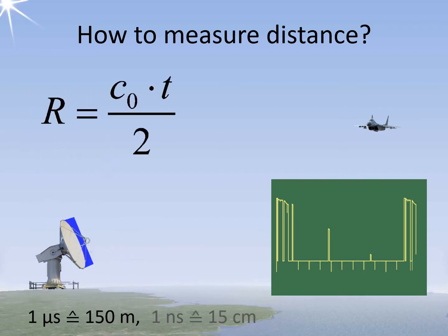For the runtime measurement, the way there and the return path of the propagating electromagnetic wave must be considered. Therefore, for monostatic radar sets, the product of the propagation speed, here, the speed of light, c0, and the measured runtime, t, must be halved.